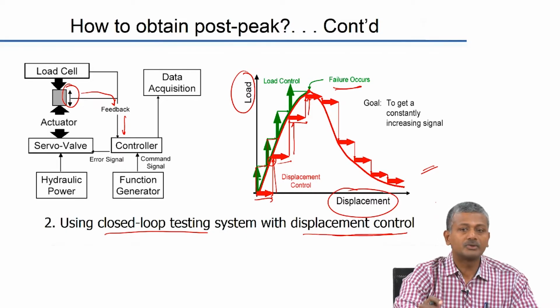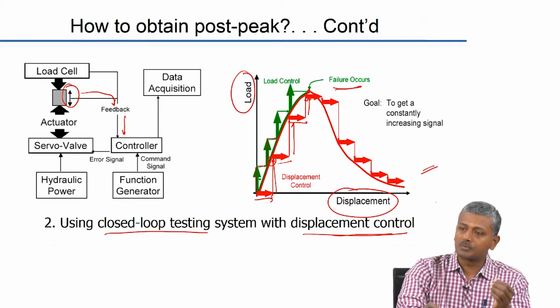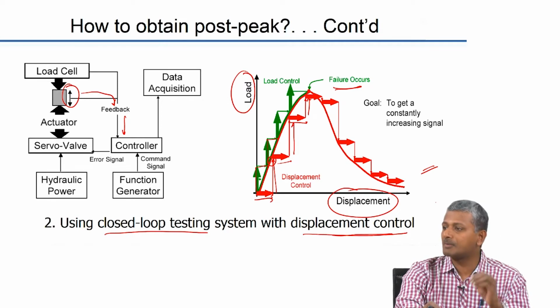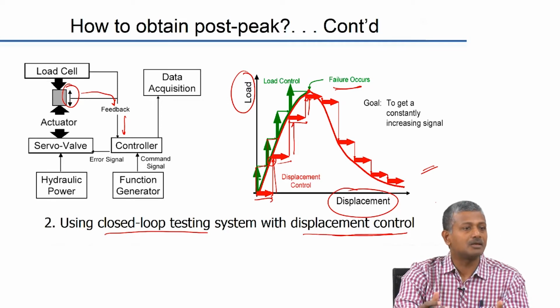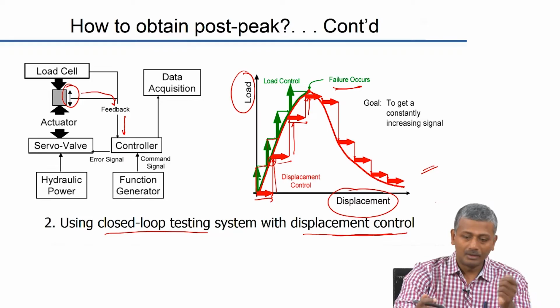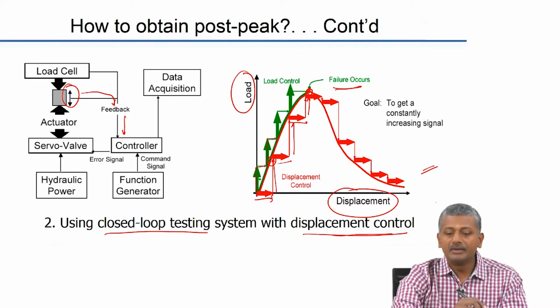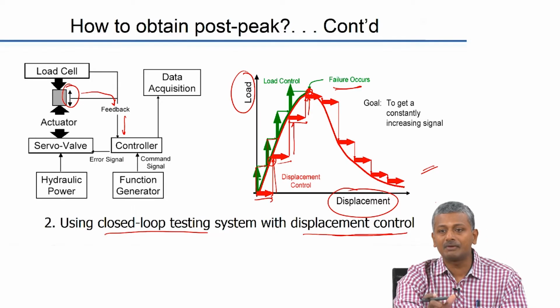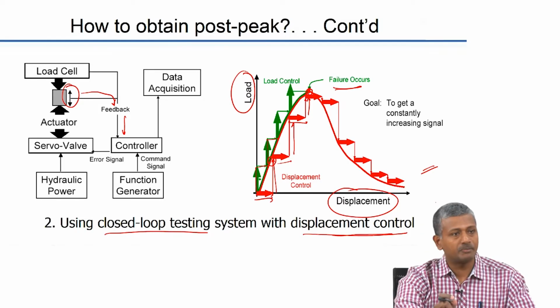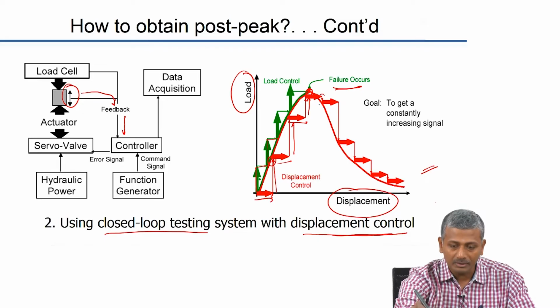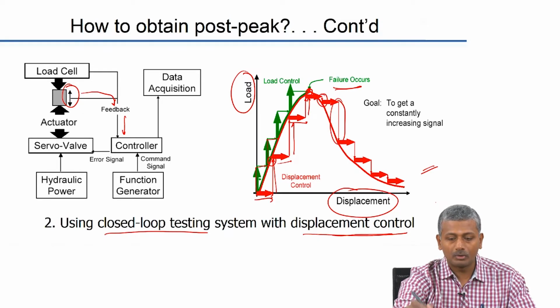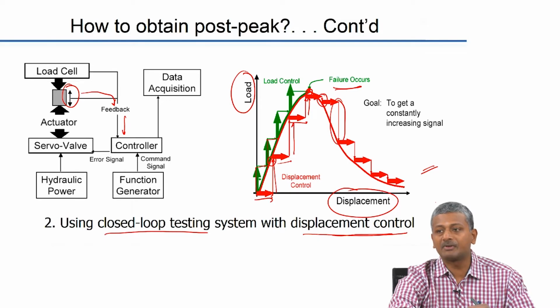Okay. So, that means you need smaller and smaller loads to actually produce the same level of displacement of the material as it gets weaker and weaker, that is expected. But what happens beyond the peak is that now to register that level of displacement in the system, you actually need lesser load than what you had previously. Okay. So, actually you need a lesser amount of load to register the same level of displacement.